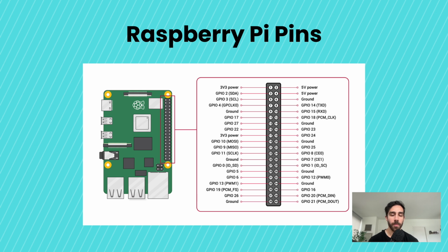And there are also special purpose I2C pins used to talk to sensors and devices like temperature or motion sensors. We'll be using I2C pins in the next segment, where we'll be interacting with a temperature sensor. We also have some other special purpose pins like SPI pins. SPI is great for faster communication with components like displays or flash storage. We also have UART pins. This is used for serial communication, such as connecting to a GPS module, an external Bluetooth module, and just any device that uses serial communication. We won't be using UART in this course, but if you are working with Raspberry Pi in the future, you are bound to interact with some module that requires a UART pin, and thankfully the Raspberry Pi has those.